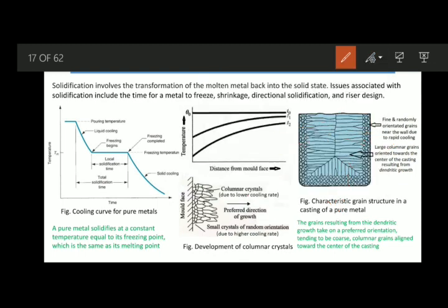So in this particular case, what basically happened is that initially some columnar grains, that means grains which look like a column, develop, and after that they sometimes form certain lateral branches, and this kind of growth is known as dendritic growth. And this kind of dendritic growth doesn't only occur in pure metals, but also occurs in alloys. Okay, so there are sometimes tree-like structures.